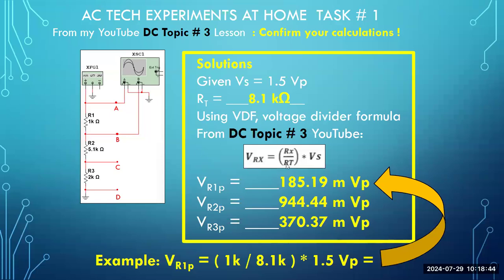This formula of Rx over RT represents a proportion of how the string of 3 resistors actually divides the voltage. Again, that's review of some previous topics, but if you hadn't seen those or don't recall that concept, that principle of series circuits, it doesn't hurt for us to review it.